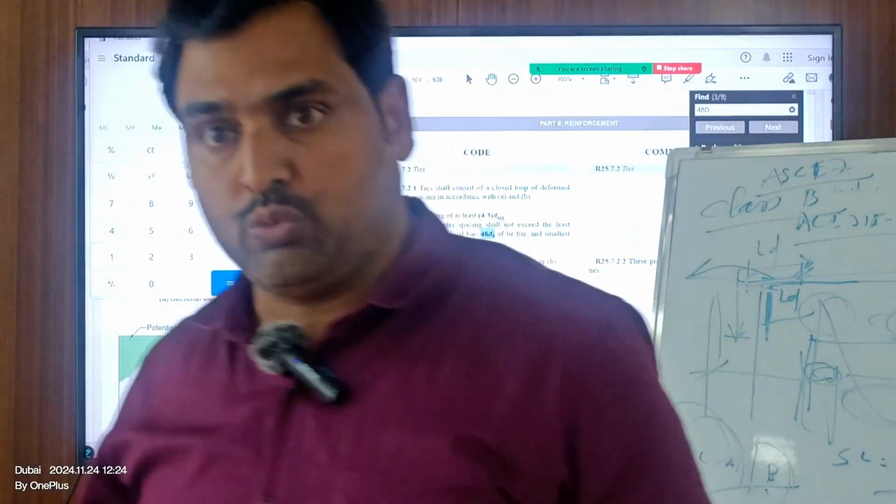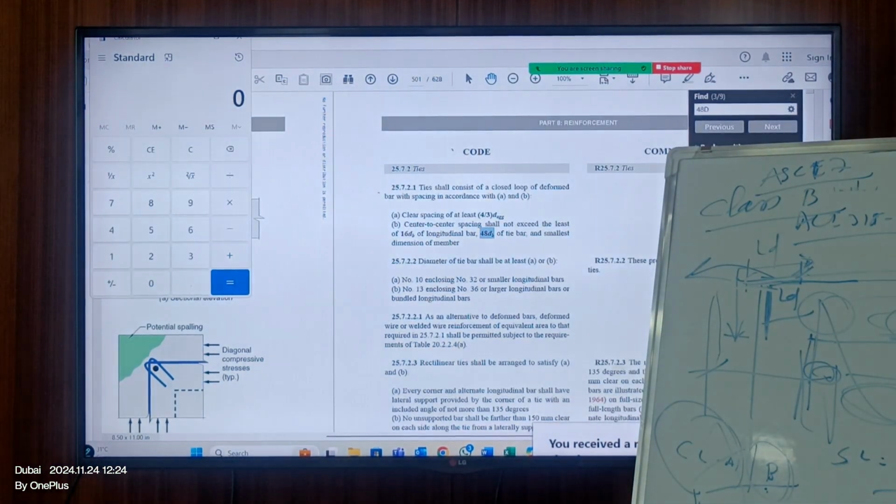The one clause which I read actually, remember, even the 12 times of diameters, the straight extension is not going to give you the additional anchorage length. So where is this clause? The clause is very small letter right below the table. You are getting a point. But people will leave this line, will take these 12 times of diameters, will insist you because they did not read the line which is right below the table.